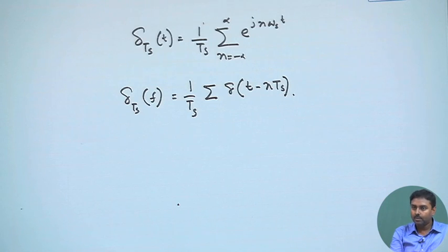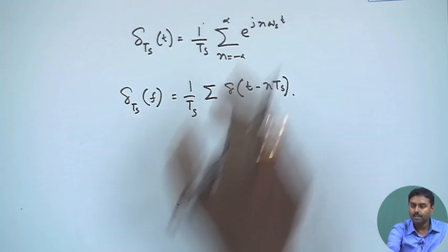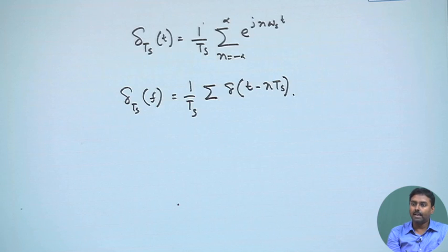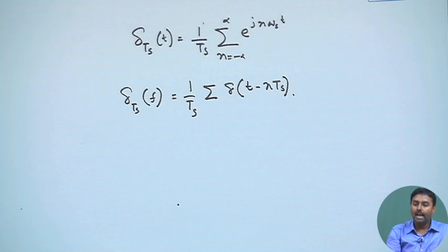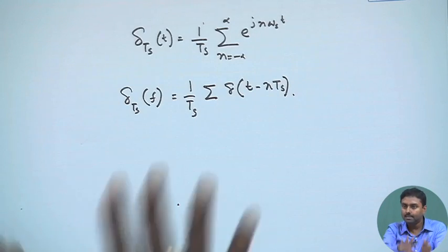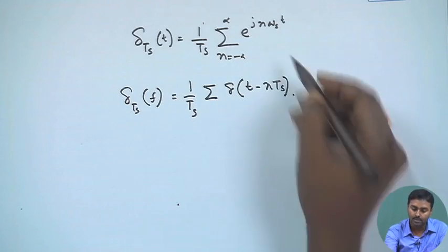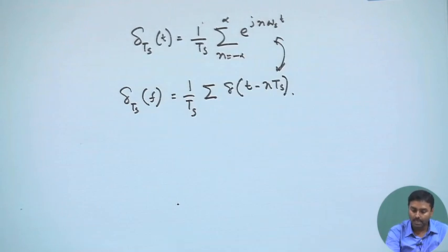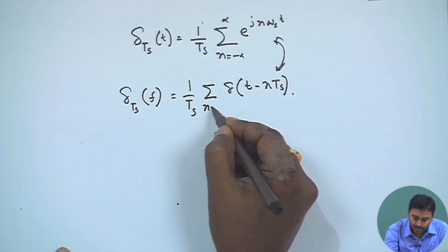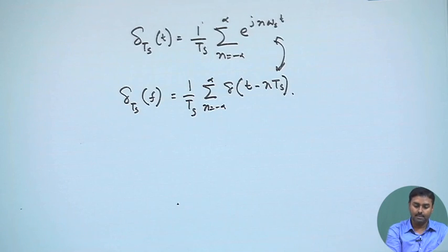this is something we already know, that if I have this, I can get a time period accordingly, which is 2 pi by Ts. This can be represented at Ts, it will be creating delta. This is something we have already known. This is the relationship, Fourier conjugate relationship, e to the power minus j 2 pi fs t will create a delta function at fs. Okay. So, this I already know. So, it will be just a summation of delta functions, that is very good.